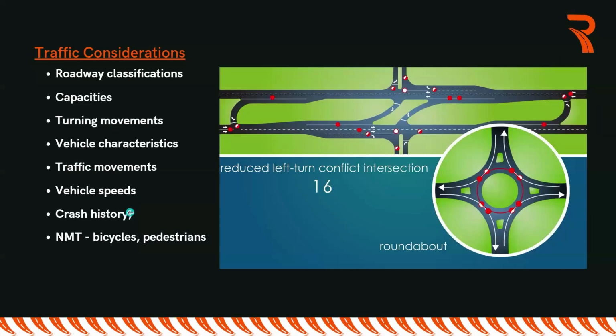And then we'll be talking about, when it comes to junction design speed, there is a rule of thumb, and I'm going to state it to you now. We use the design speed of the major road to design the intersection. So if the major road design speed is 80 kilometers per hour, how do we determine the design speed of the intersection at that specific point? These are the two rules of thumb that I'm going to give to you. When I talk about rules of thumb, it means they are generally accepted approaches, but they may vary according to design specifications in different countries.